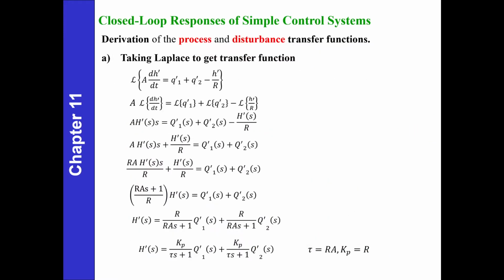So we continue by taking the Laplace transform of this dynamic model. Just do the Laplace transform so that you will get the S domain. Previously, it was the T domain. T domain and S domain. So here you rearrange everything until you get this form. From these two, can you differentiate which one should be GP and which one should be GD?